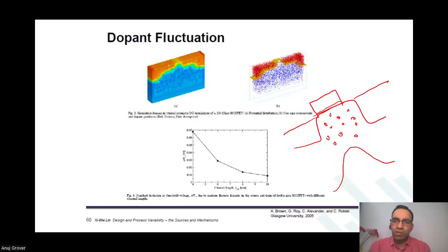Or sometimes there will be 21, sometimes there will be 19. It's a natural process, no? Yes, sir. You're not placing dopants one by one. You're just bombarding and you're letting them diffuse. There are bound to be variations. But the machinery which I'm bombarding with, I have the frequency, everything in control, right? So I can be sure how much I'm bombarding.